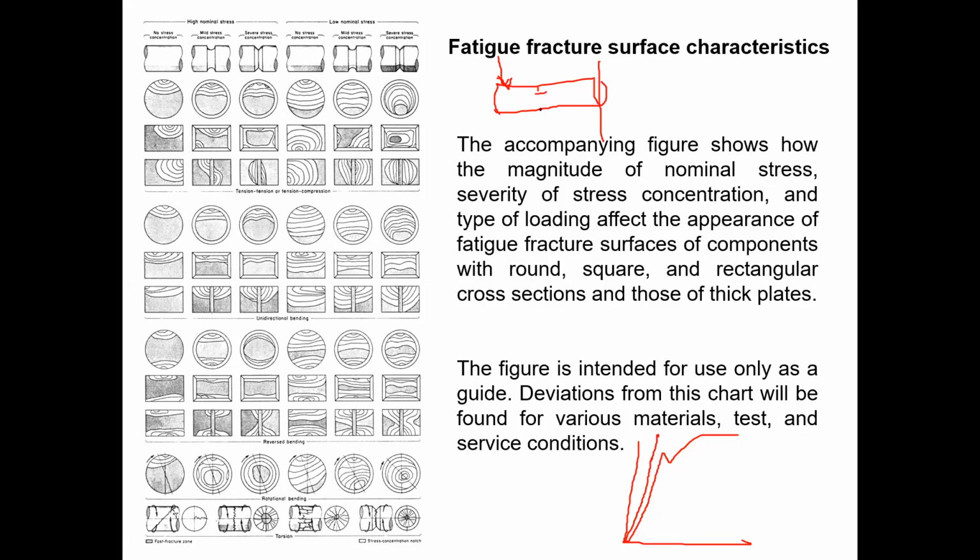This is the effective cross-sectional area, isn't it? So when the crack propagates, what happens? The effective cross-sectional area will be reduced. So somewhere here, this will be the effective cross-sectional area due to this crack propagation. Due to that reduction, this load we cannot withstand with the cross section. It will suddenly fail as a brittle material. Until this point, it acts as a ductile material, but with the effective cross-sectional area reduction, it acts as a brittle material, because this force applied to withstand with this much cross section has now reduced to a very low value. So with that load, it cannot withstand. Suddenly fail.